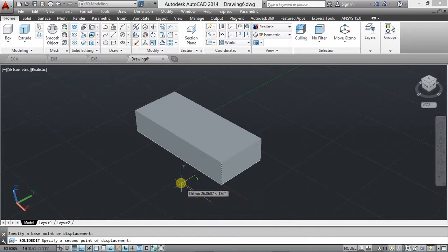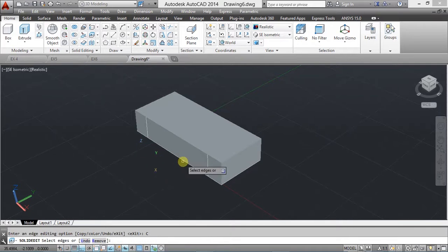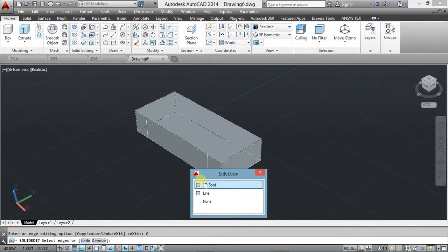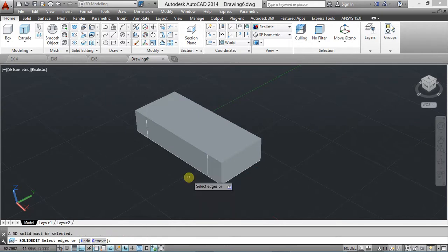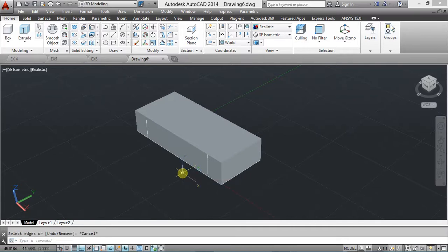This side 14, okay. Copy again this side, select, enter, draw to the direction 14, enter, okay. Copy again. Want to copy this down, you cannot copy, okay, because there is a line, the sketch down there, that sketch is interfering.